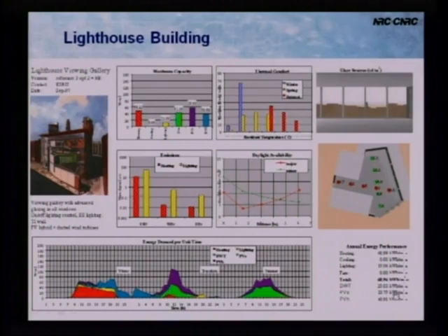So what you can see here is that in terms of the renewable energy sources, there's more than enough energy in the year to match that demand. The problem is that most of that's getting generated in summer and spring when there is no demand. So you've got this complete temporal mismatch between your renewable energy sources and your demands in the building. And that's one of the big challenges of integrating renewable energies into buildings.